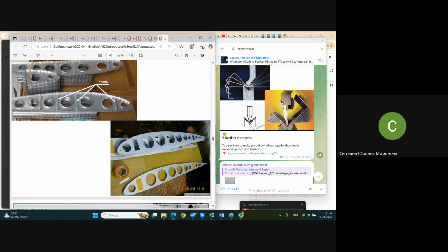You will have only, you may call it die block, consider it die block or punch. Actually, they are punches. By this terminology, with male part, female part, they are punches because they are intruding into the part, inside of the workpiece. But they may have different names.